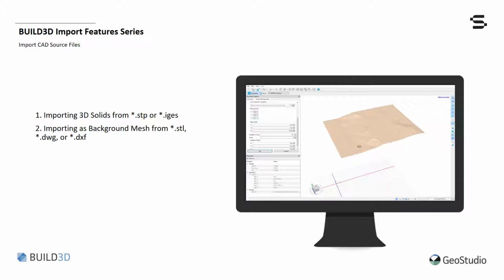Surface meshes that have been created in CAD software can be imported as a background mesh in Build 3D. A background mesh can then be used for 3D sketching or for the creation of a NURB surface, such as topography. File formats supported in this import type include DWG, DXF, or STL format.